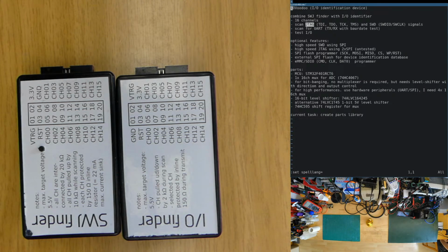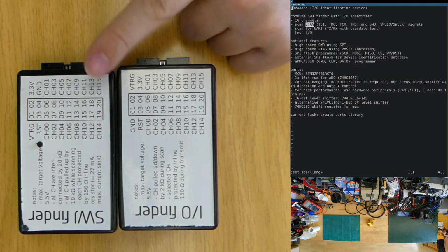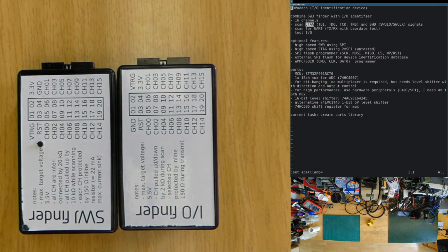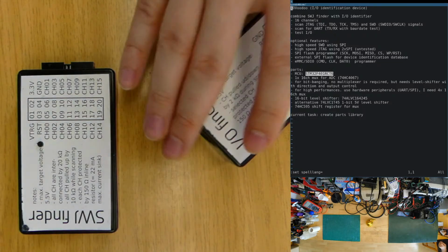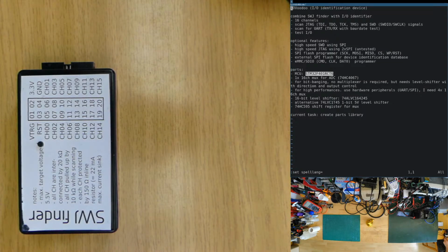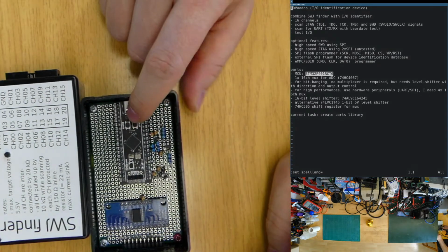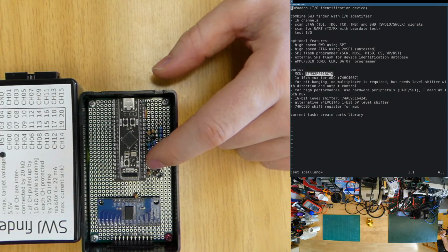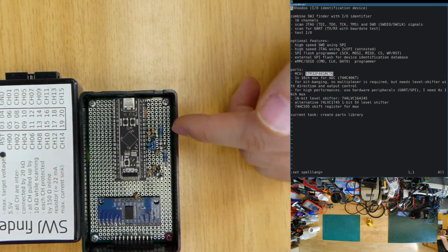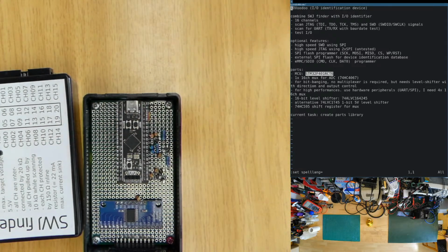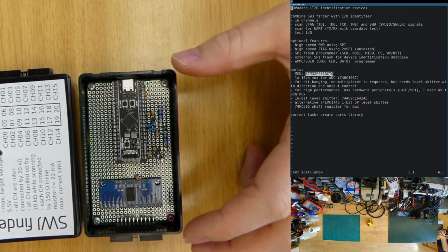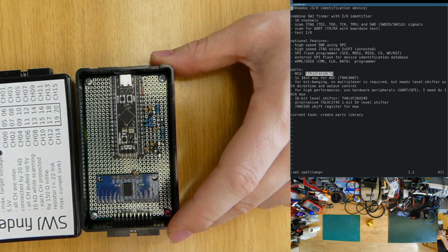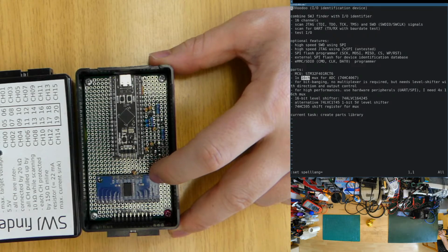So that's the IOVoodoo. So why did I choose this? In the first two streams, I explained what this is. We decided about the parts, and I decided to use the STM32F401 because I have lots of development boards using this thing. This is the development board I was using, and it worked pretty well. This is why I decided I already have code implemented for both of these things using this microcontroller, so why not just reuse the code? And to do everything I need analog multiplexers for measuring.